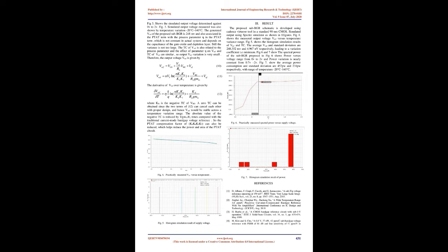The current through Q0 should not be too small, so as not to increase the required positive TC of the proportional to absolute temperature, PTAT, voltage. To optimize the power and area, the current IR through R2 is chosen to be 3 times the current through Q0. The combination of the PMOS with a P and polyresistor R2 produces a PTAT current flow.